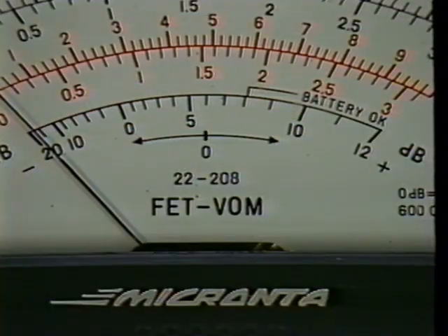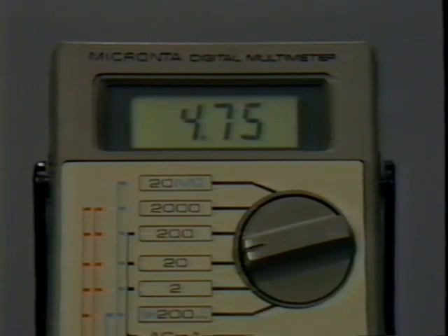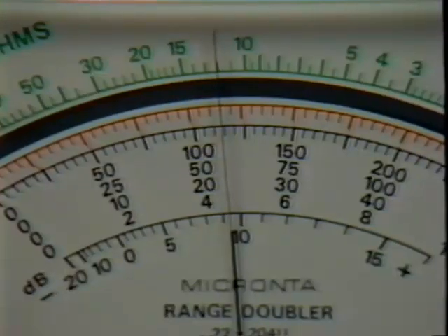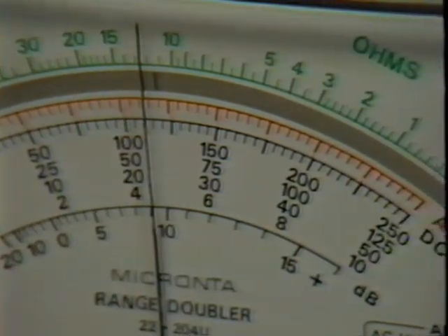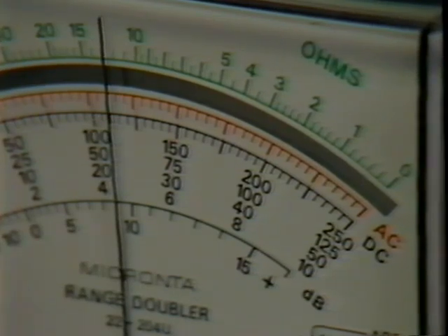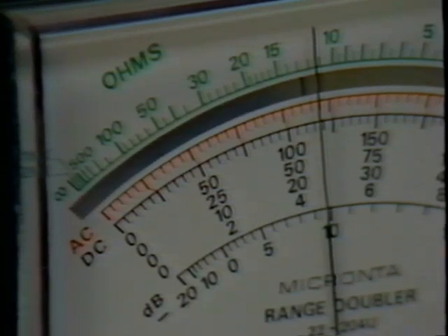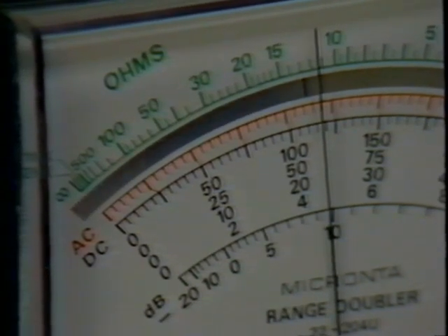The way to offset this disadvantage is to use a meter with a high ohms per volt rating, or to use an active component meter like a vacuum tube voltmeter or an FET meter. When measuring steady voltages, the DVM is also more accurate and easier to read than an analog device. There are two reasons for this. The first is that analog meter readings are subject to errors of parallax. This means that your reading appears to vary as you view the meter from different angles. The DVM presents readings on a numeric display, so this type of error does not occur.